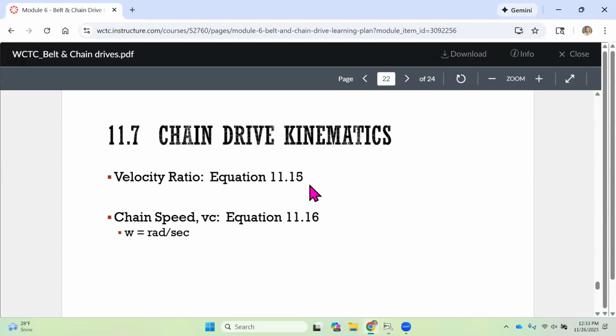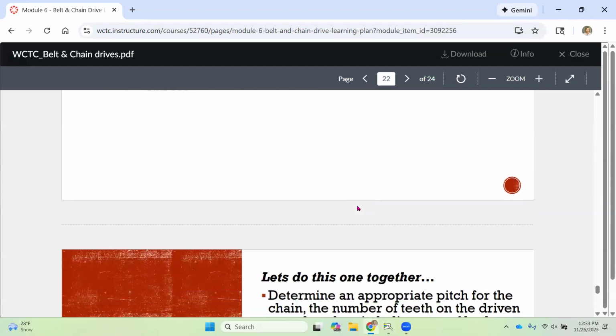As you know, problems are going to be given in RPMs. And if we're asked to find out what is an output speed and angular velocity, then we need to report it in RPMs as well. But in and out of this equation, radians per second or radians per minute, whichever seems appropriate for the application. So those are those two equations, which we'll revisit again.